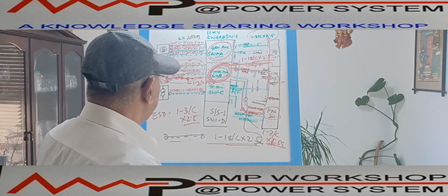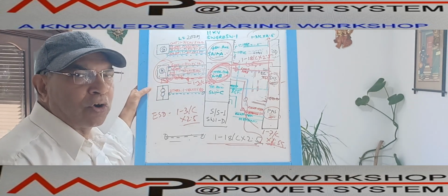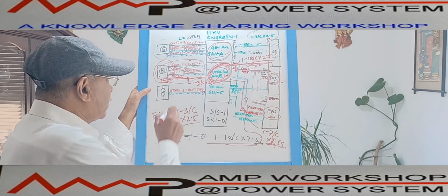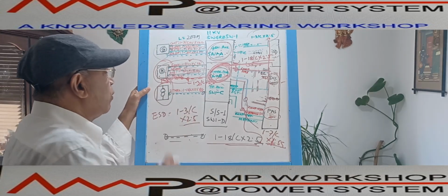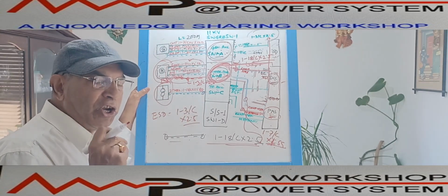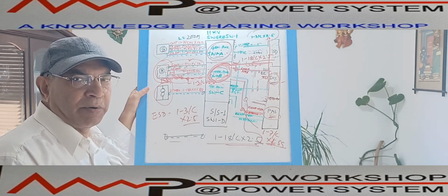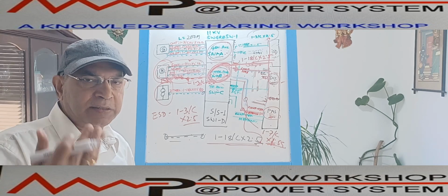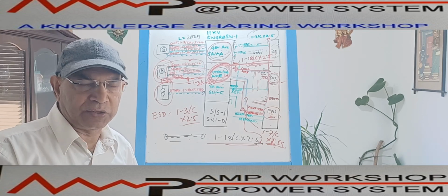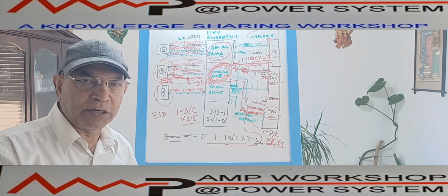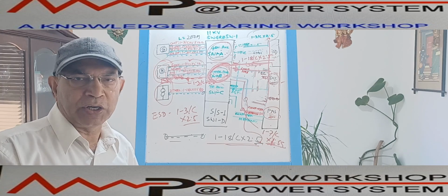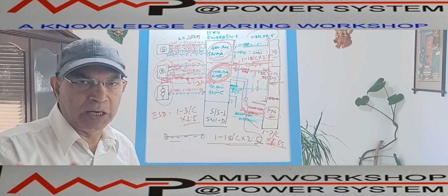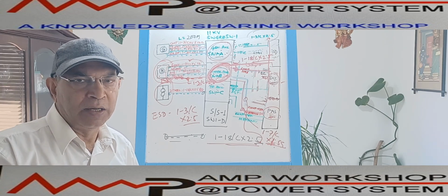In the case of the transformer panel, we do not monitor transformer winding temperature. So the only thing we need from the transformer skid is one control cable coming to monitor the various statuses of the transformer. The transformer has various devices mounted on it, various indicators like oil temperature indicator, oil level indicator, winding temperature indicator, and pressure relief device or Buchholz relay. These are the 4 major devices mounted on the transformer.